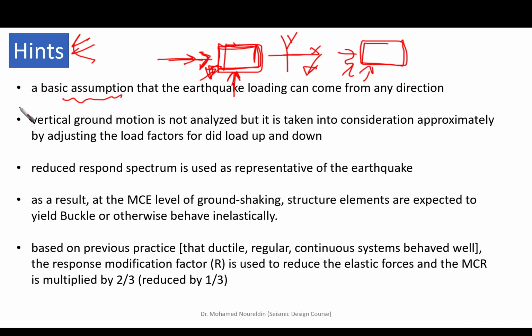Okay. Another important hint is that vertical ground motion is not analyzed. Take care of this. It is taken into consideration approximately by adjusting the load factors for load up and down.